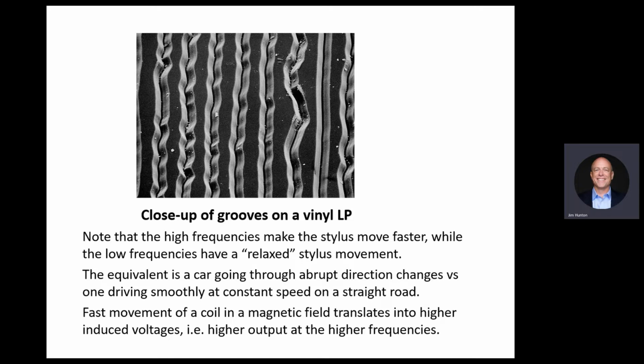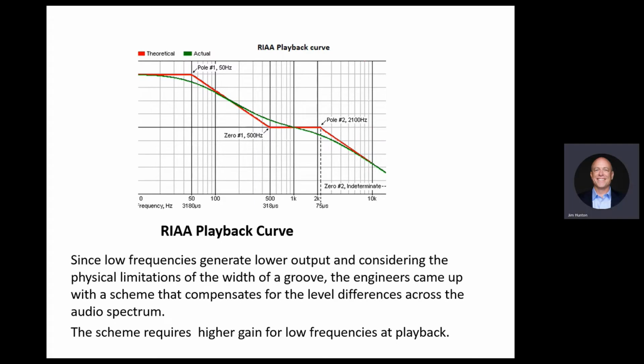That's not acceptable, because then we don't have enough space. So the other solution is, of course, to change the gain. By definition, we will amplify the low frequency, the 50 hertz and below, a lot. The 1 kilohertz mid band is going to be amplified by whatever we specify for the amplifier.